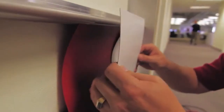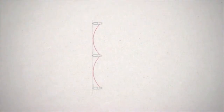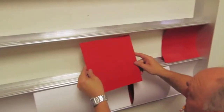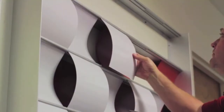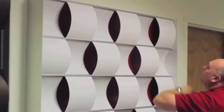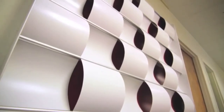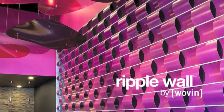Your shadow tiles should always meet behind the concave ripple tile in order to hide the join. Be sure to place the shadow tiles in the channel shown and not the groove for the ripple tiles. When placed correctly, ripple tiles alternate in curvature, with a convex tile always followed by a concave in both directions. With a wide variety of finishes available, such as wood, color, aluminum, polyresin, and Vario Eco Resin, Ripple Wall provides an exciting element to any space.